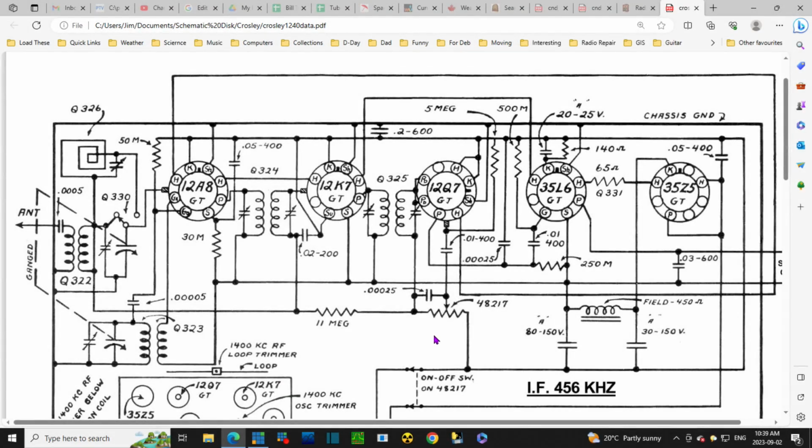So why without that capacitor would this radio not receive any stations? Yet it sounded like it was kind of working. This is the capacitor here. So you picture this removed completely. Well, wait a minute. Let's go the other way around. What is it doing? So this side is hooked up to B minus. So from a signal point of view, B minus is here, or ground. Ground is here. It's grounding this line, signal-wise. It's allowing DC to be on it, but not allowing any signal to be on it.